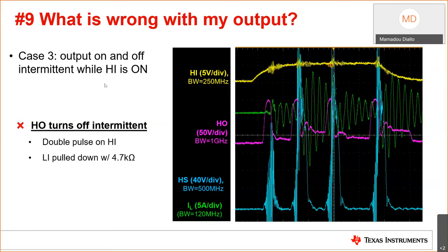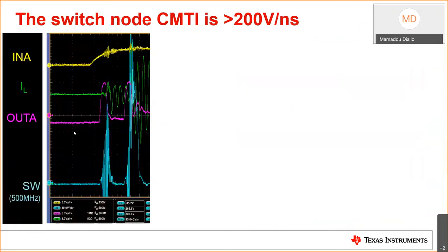In each case, you have different behaviors of the HO output. What's going to happen is you'll see these different profiles and different failure rates, but essentially coming from the same critical issue, which is DVDT, at the essence of it. Let's review what we have here. Again, false logic, yes, absolutely. What's happening in all three of these cases is really DVDT being the main issue.